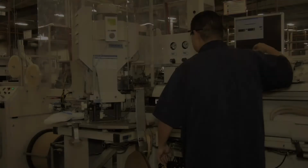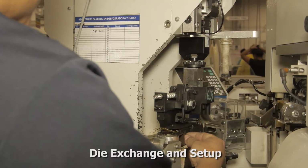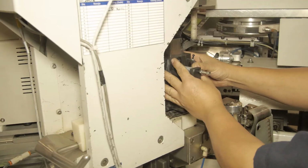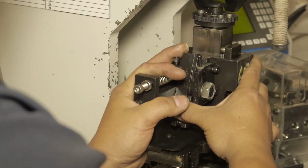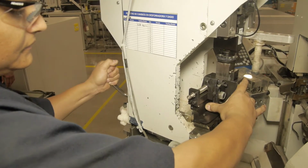Different dies are used depending on the terminal type used in the cable assembly. The die that is mentioned in the cutting ticket should be used for that particular job. Setting up a die is a very precise and important part of setting up the equipment. Improper setup can lead to faulty crimping and high scrap.